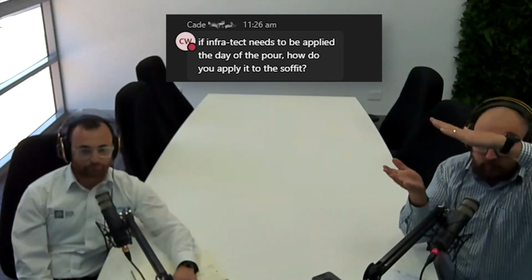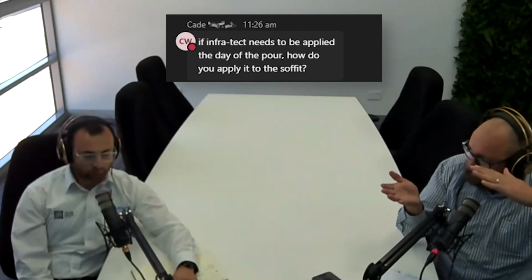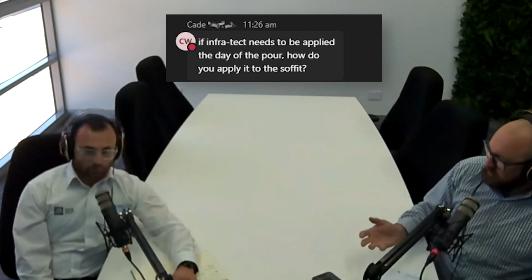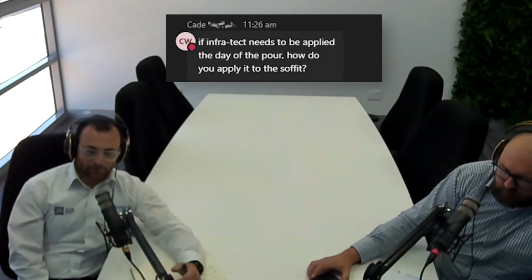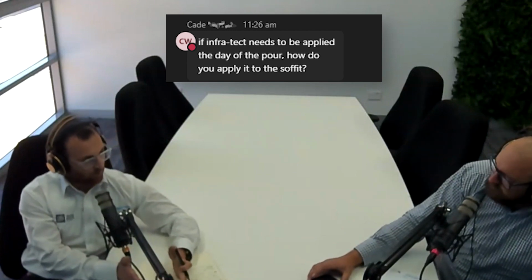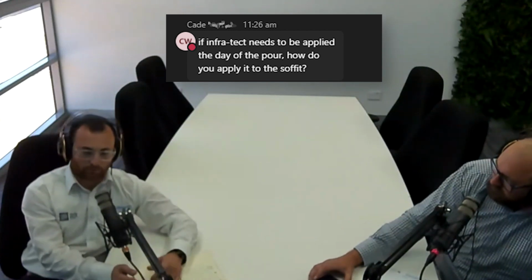And then if we're locking moisture in from the top, we're getting really, really well cured concrete. That's more about protecting against carbonation and that sort of thing getting into the concrete from underneath. It would almost fall into a retro style application. Based on the fact that we spray that once the formwork has been removed, we're then looking at that long-term durability, because it's done prior to handover, which is when you start getting vehicles trafficking around a slab, which is where you get your carbonation rising from, et cetera.